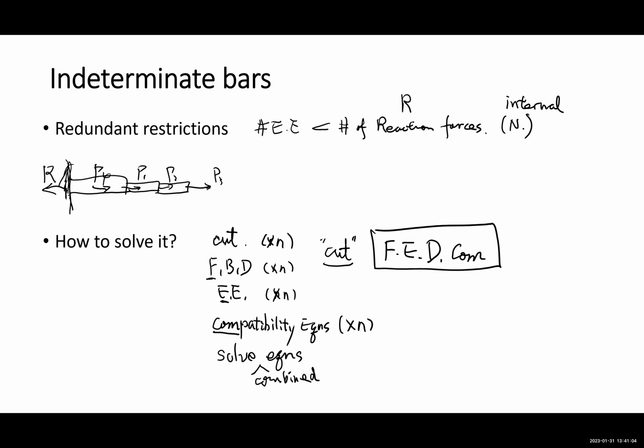Determinate. Because you have only one restriction, right? Doesn't matter how many loads you have. The load is known. So the equation of equilibrium, you can write, in this case, it's only one, but you have only one unknown. So the reaction, how many reaction forces, that's the initial way you use to judge determinate or indeterminate. Yeah, so this is a very good question.